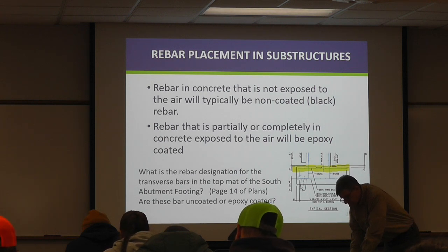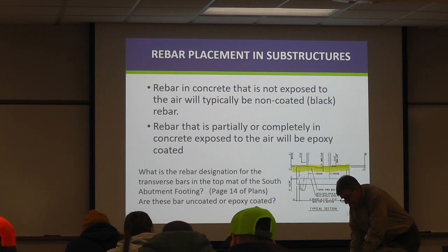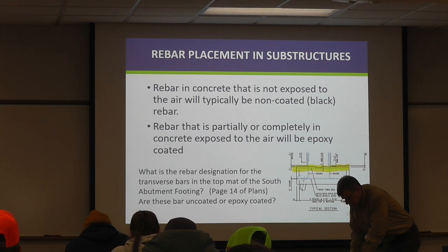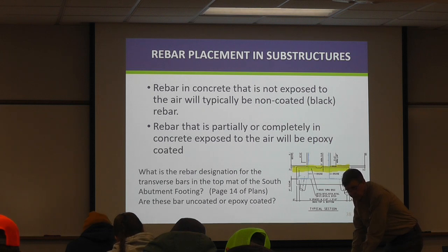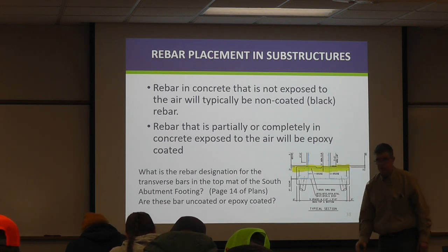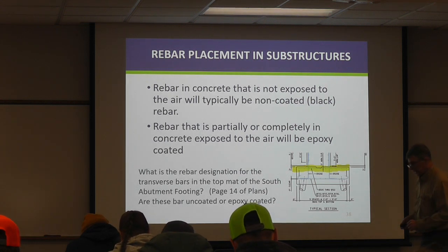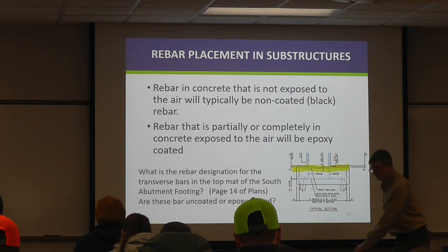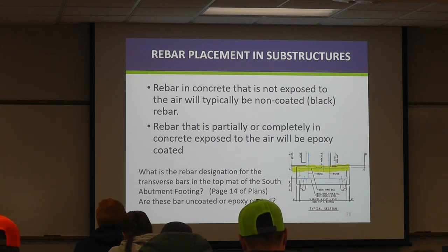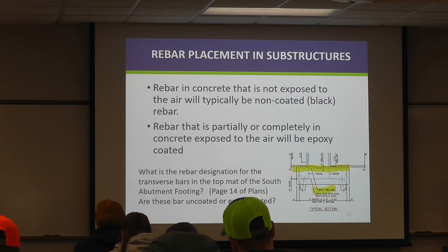See, so in our bill of reinforcement, bar numbers on the left and the number of bars and then the length. And so we are from here able to see that there's some little tiny bars here. The last one is only 3 feet long. Almost to the point why I even bother putting a bar in that's only 3 feet long. There'd be another way to do that, and that's called a series. And we'll be coming up here pretty soon, I think.